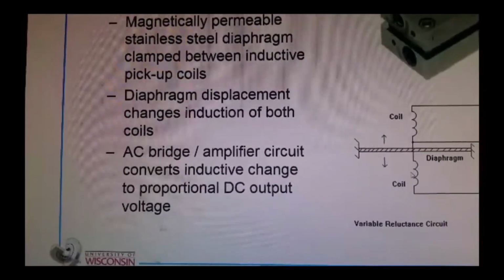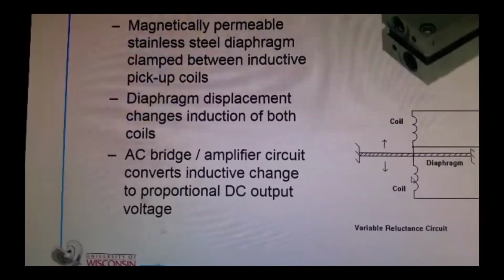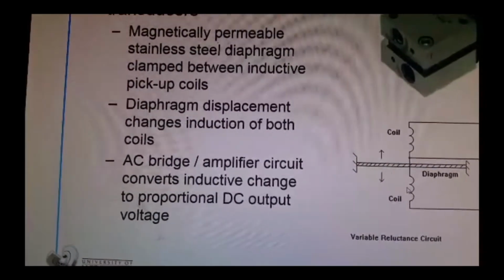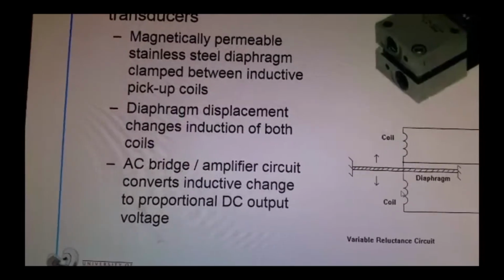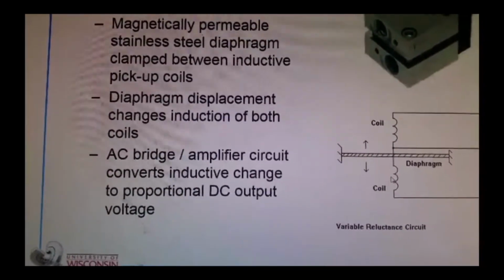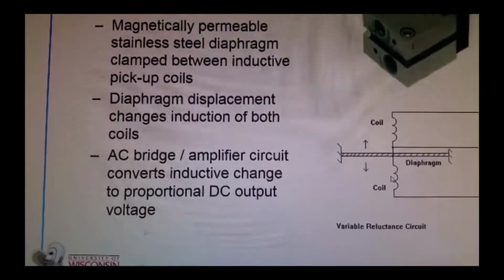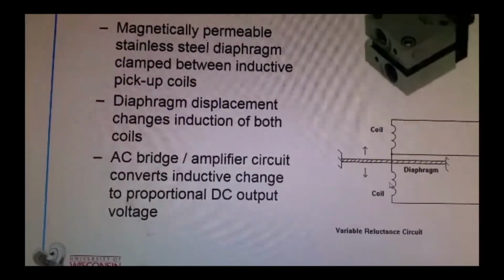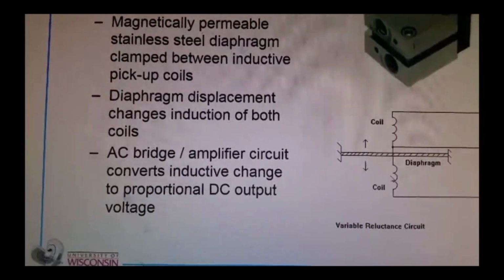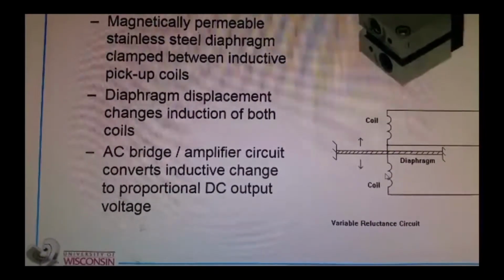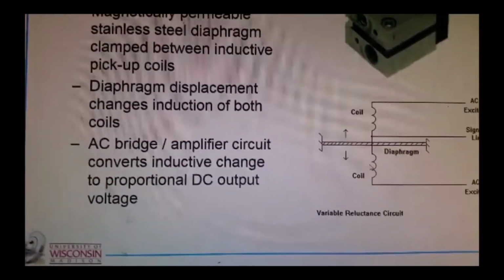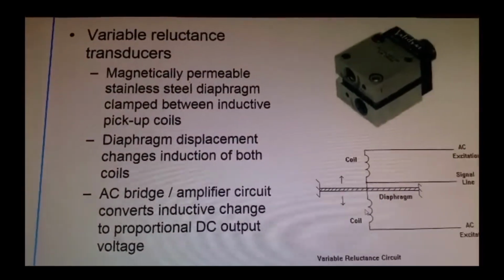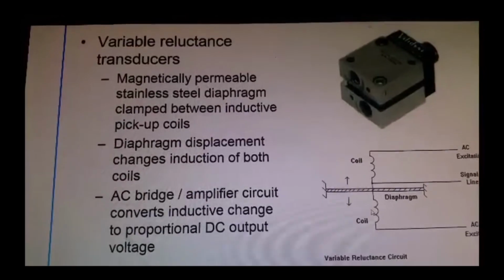A pressure transducer senses pressure from the outside mechanically, and it will produce an electric signal in response to these changes. When it comes to the variable reluctance pressure transducer, a sensing diaphragm changes position with pressure, inductively changing the impedance of two sensing coils. This change produces an electric signal. Next, we'll show you an example of a variable reluctance transducer.